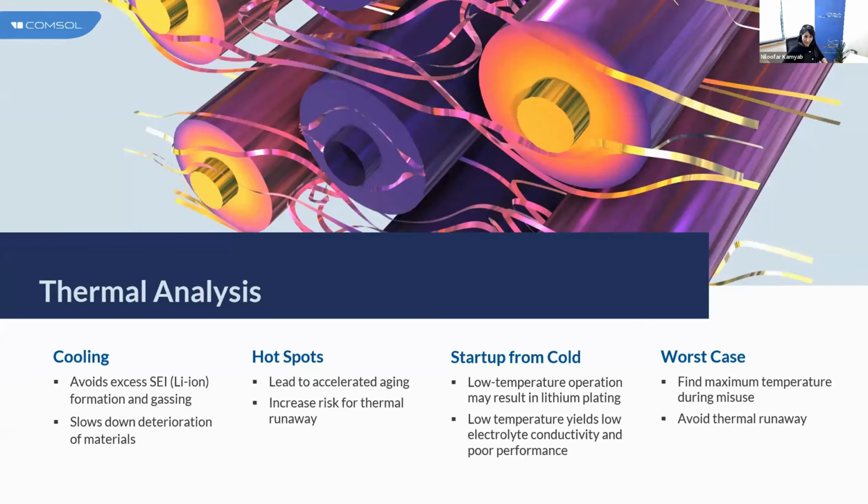And then we get to thermal analysis, which I touched on in the beginning when I was talking about multiphysics, that batteries by nature are multiphysics. No matter what chemistry you work on, all the chemistries that I mentioned, you have very good reason to be concerned about temperature, because temperature affects your cell performance and temperature affects cell degradation. In fact, if you do not consider temperature, in many cases you're making a very simplified assumption that temperature doesn't affect your chemistry, which in many cases is not a good assumption.